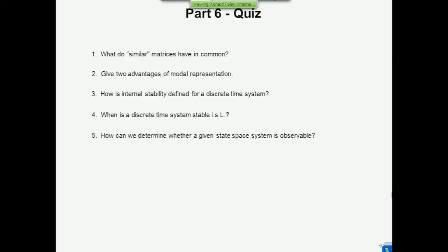There was a test, too. You construct the observability matrix Q. It was C transpose, A transpose, C transpose, and so on. Those partitions, that should have a rank of n, full rank on that observability matrix. So there's 2 different ways of determining that.